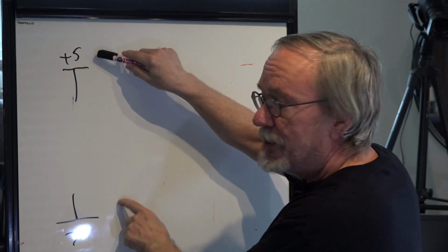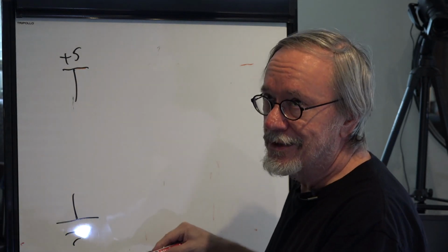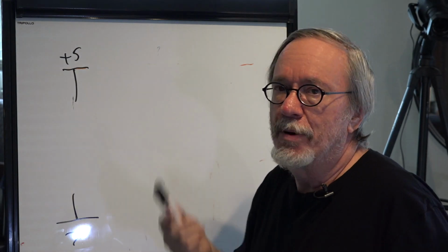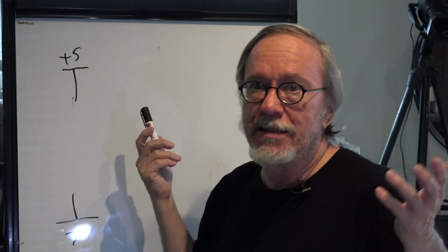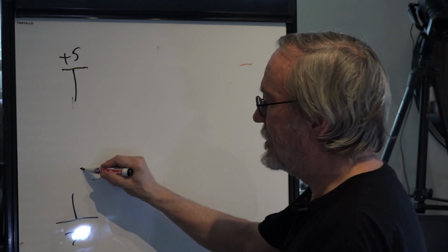Distributes audio too. And it has a positive bias. Positive bias just means the video is up in the air. The video is going to be up in between these two rails. Very helpful. If it fell down too low, and there are reasons that can happen, the comparator would go, I can't see down that far. I'd love to pick off your sync, but it's buried in the ground. Video is down here somewhere.